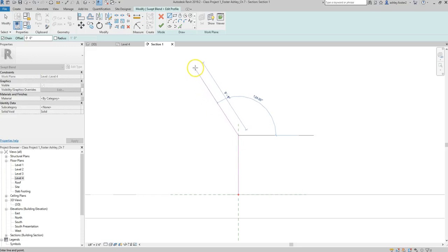Let's make something that's very curvy, and we're going to draw almost like a chair shape. So we can just slightly come out here to the left of the reference plane, and then just start clicking to add little reference points to show where the spline will move and curve back and forth.